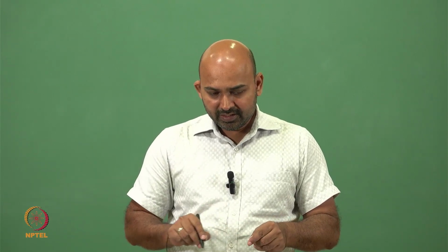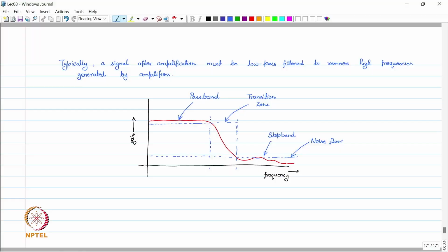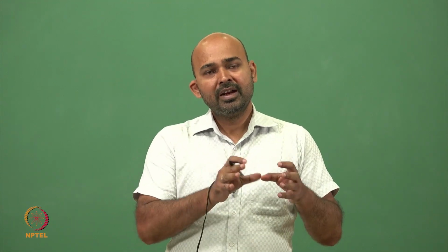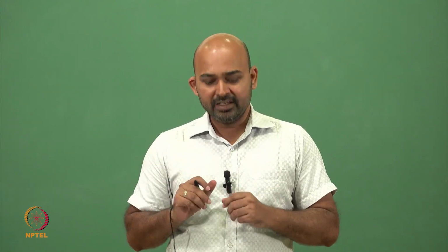Now this filter has a certain response, which we can see for the low frequencies which are close to the origin. For these low frequencies the filter has a high gain. It means these low frequencies will come and smoothly pass through this filter because of this high gain.